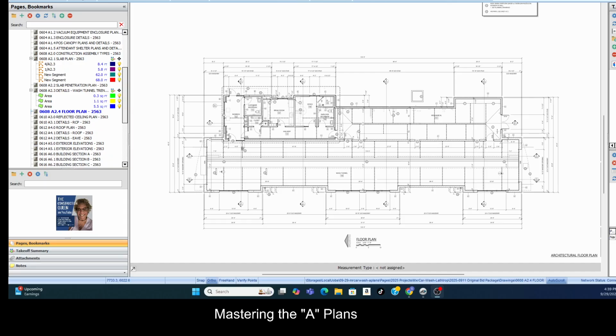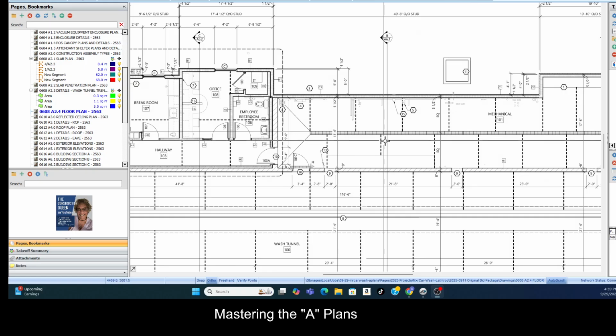Okay, now on the floor plan and the section views related to the floor plan, anyone that's working on any aspect of the project, those section views are for you. I always say framer because section views are typically used for the framer to determine heights of walls. But also, the roofer can use those same section views to determine the framing details.